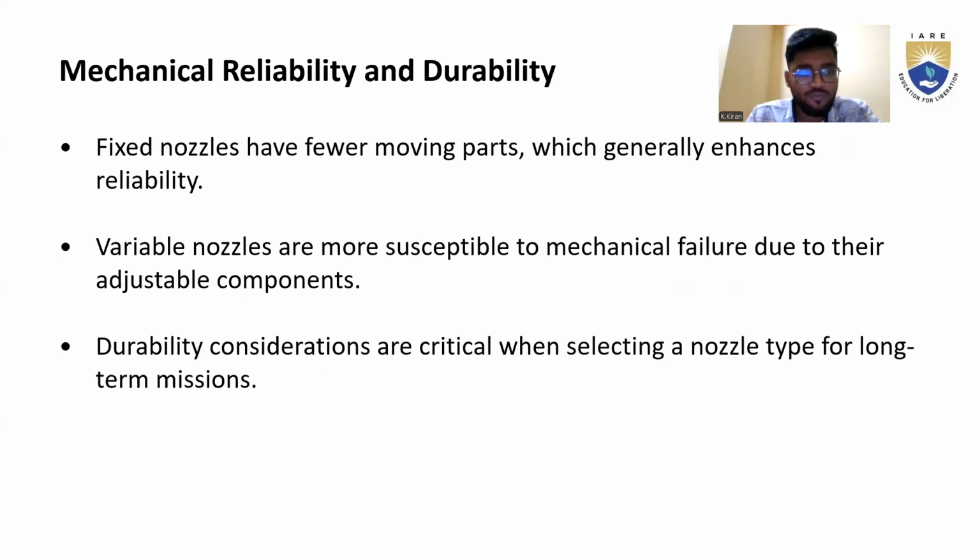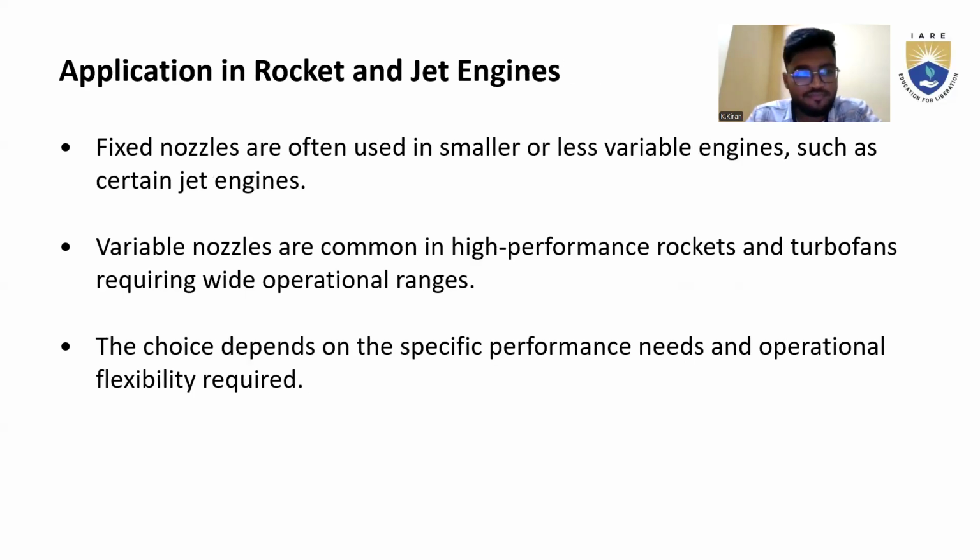Mechanical reliability versus durability. Reliability means that the fixed nozzle has few moving parts, and through that it is reliable. In the durability consideration of nozzles, long-term missions matter, because selecting a nozzle type is critical given the risk of failure from the adjusting components.